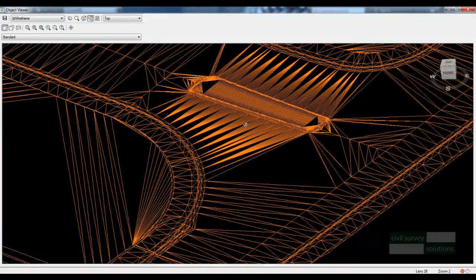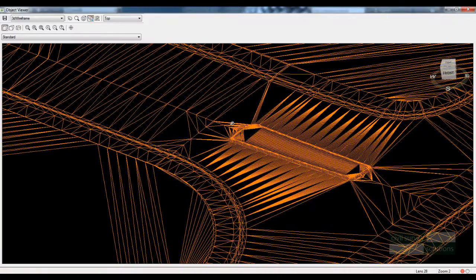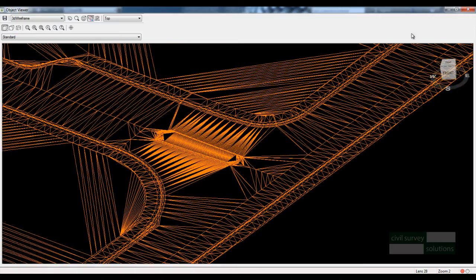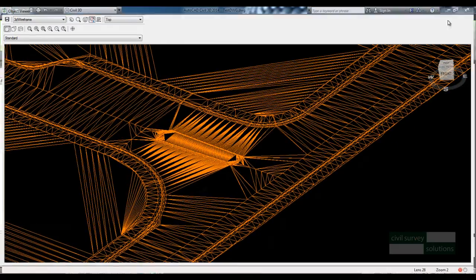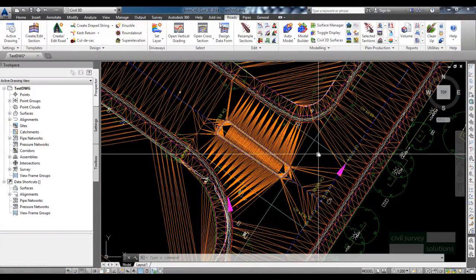As I said, you might need to swap some triangles around, even around this region here, but using Civil 3D I can make those direct edits to the surface, swapping edges or perhaps doing a smooth surface to fix up some of the triangulation at the intersection. But that's how you go about adding an island to your intersection model.